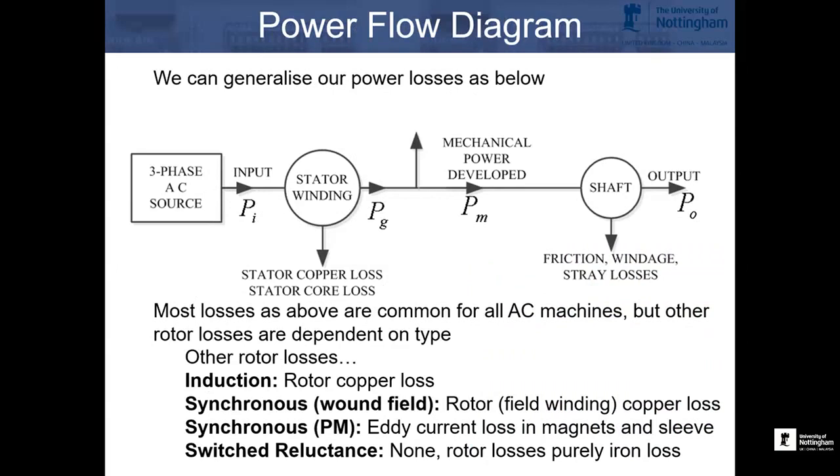But fundamentally, all this comes back to those power diagrams. So I've shown you one or two power diagrams for machines, and these are very important for thermal behaviour because these show us where our thermal losses are coming from. Pretty much every loss that we have in our various machine circuits, our machine models, manifests as some form of heat being dissipated into our machine, in the iron, in the stator and rotor copper, in the magnets, in the rotor iron, in bearing friction. So all of these heat sources appear in different points.